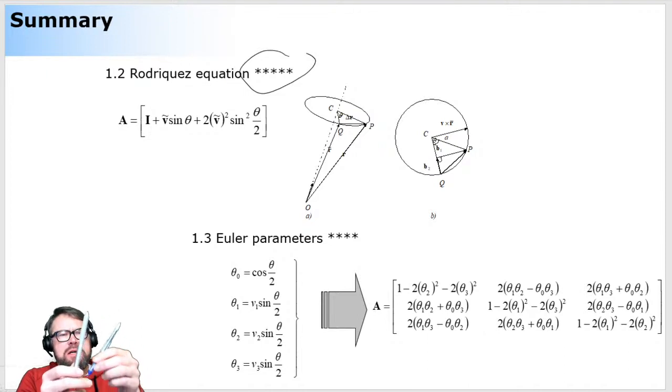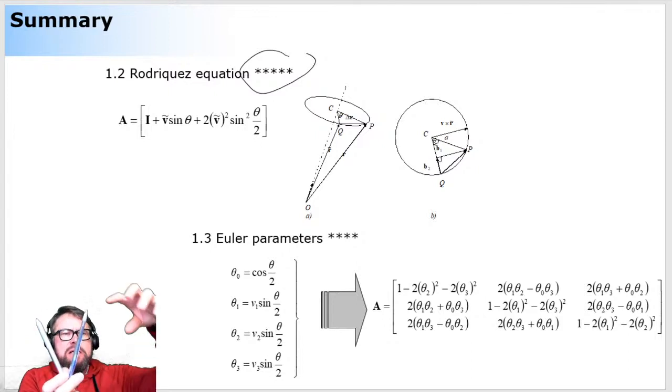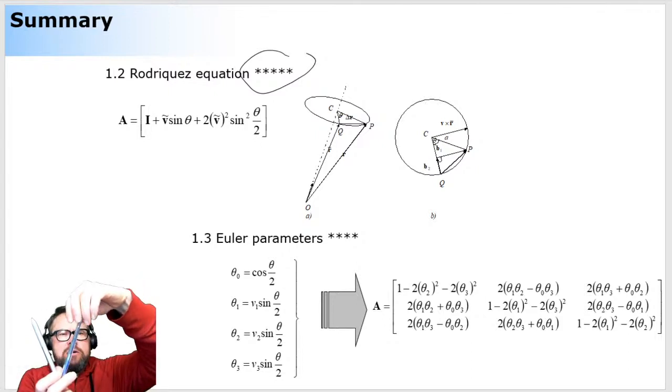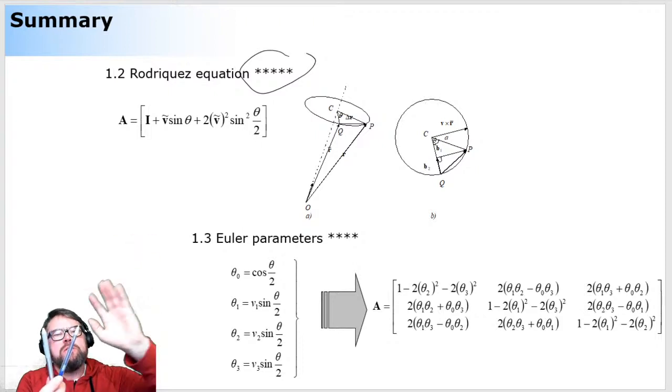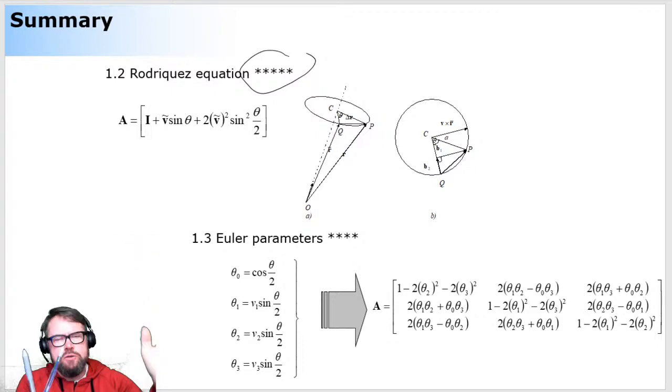What you're going to do is use a unit length vector v, and the unit length vector v will be attached to your original vector, and then you're going to take hold of the unit vector v. You will introduce a rotation of amount theta. All right. Now what you're going to do is take a look at the original vector in its original configuration and its final configuration, and you're deriving a relation between these two configurations. This relation will be your rotation matrix.